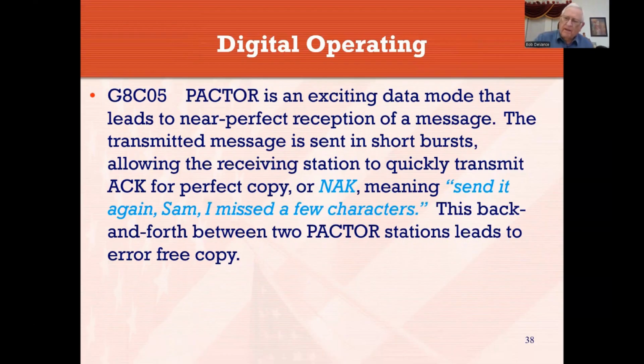Okay, transmission message is sent in short bursts, or short segments, if you want to call them that, allowing the receiving station to quickly transmit an acknowledge for a perfect copy, or a not acknowledge if it was not a perfect copy. NAK, then we usually call this ACK-NAK, just to give it something easy to say. If it sends back a NAK request, it's telling the sender, send it again because I didn't copy something correctly. And so the sender, if that's you, would send it again. And then if you get back an acknowledge, yes, I got it, then you would send the next packet. And it would go back and forth like that as long as the two can communicate.